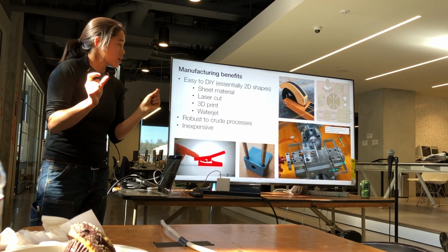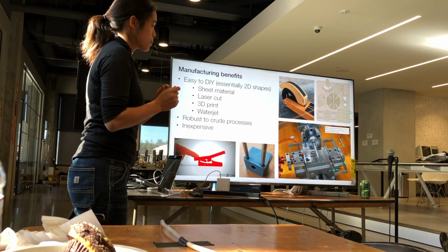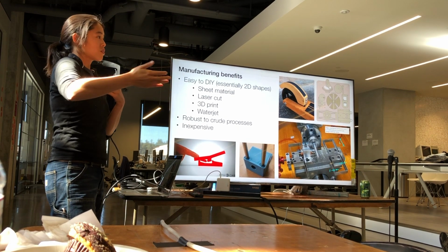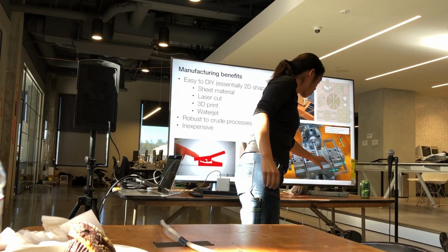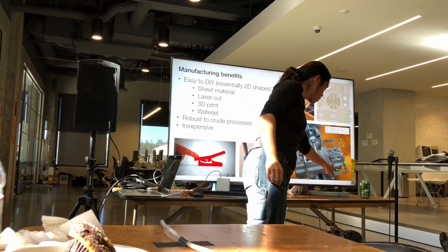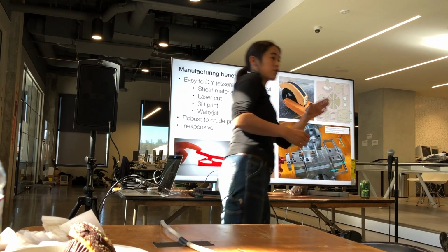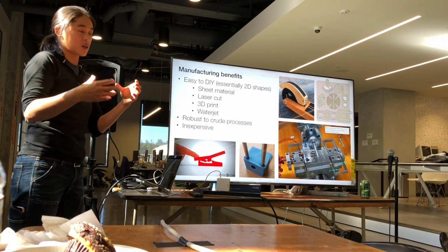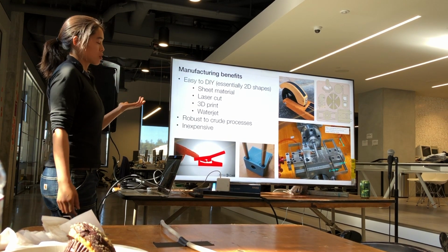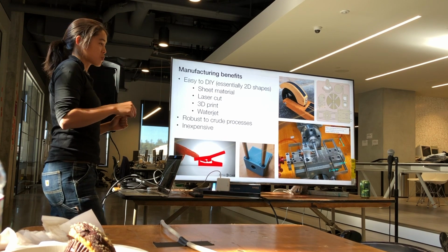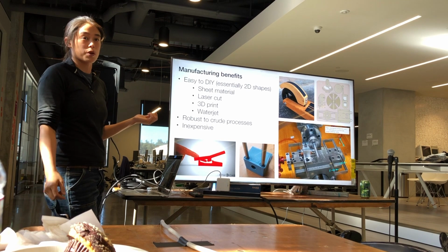So you might get some variation in the thicknesses of materials, but the relative thicknesses of everything is pretty consistent. If you cut the shape out, you might not get the exact thickness you want, but that thickness will be pretty close to the thickness of the opposing spring it's working with. So if you want, you can just punch out a bunch of parts, maybe with small variations in thickness, and then pick the one that works best for your application.